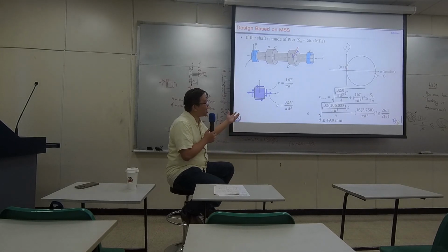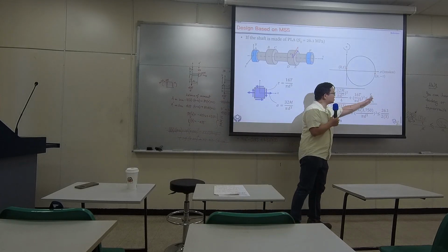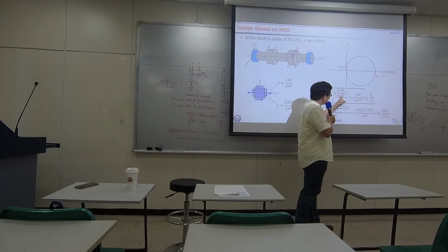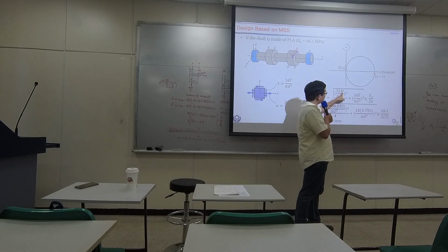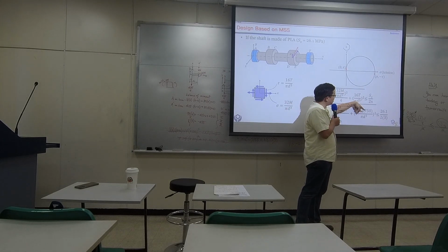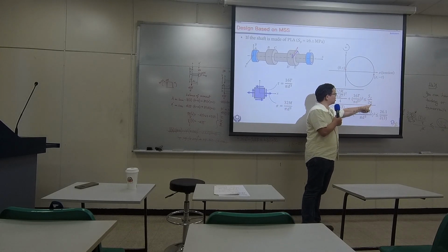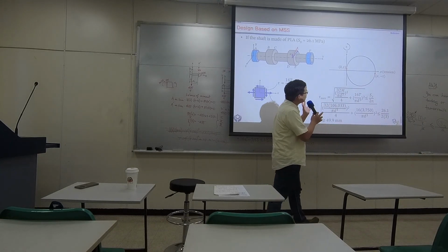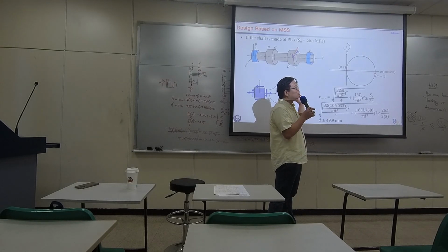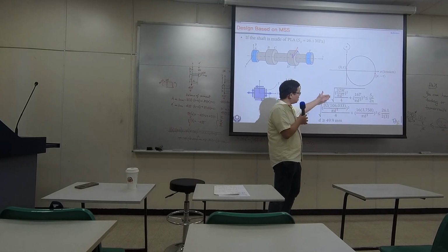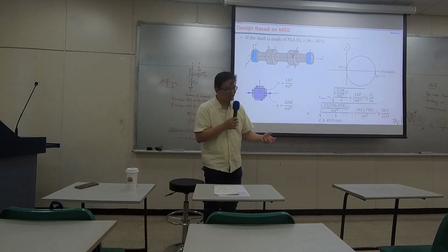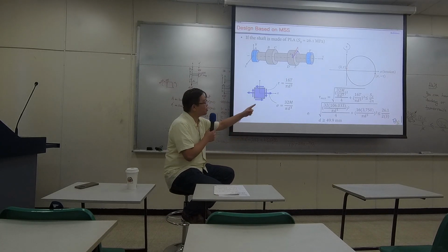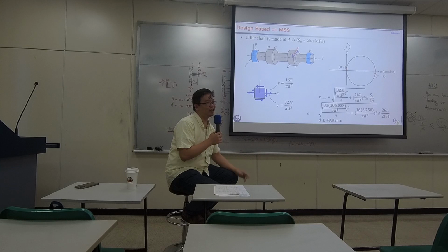Okay, so now you realize how complex everything is connected with each other. Dimensions are here, the moment you are carrying is here, torque is here, yield strength is here, safety factor is here, and they are related to each other based on the maximum shear stress model. This is the resultant equation of the maximum shear stress model. Later on, I will talk about different models. The equation looks different.